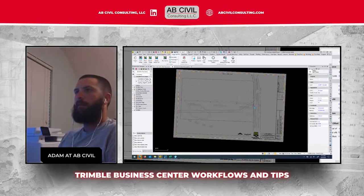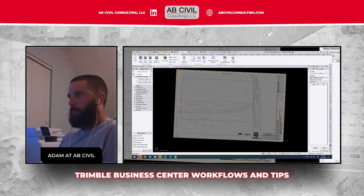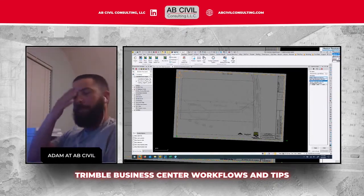I'll do that one more time. After I hit capture, if there's no plot box selected, I think it captures your screen, which we don't want to do. So if you click on here once, twice, and then click on your plot box, in case you have a dozen of them, it'll highlight that.